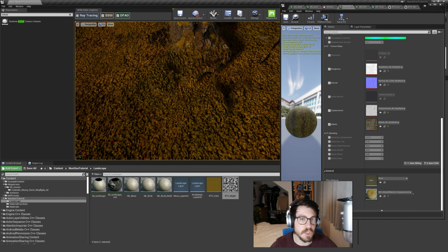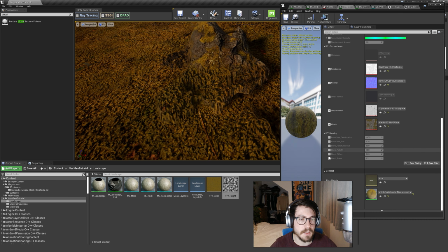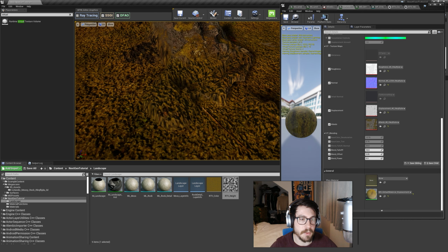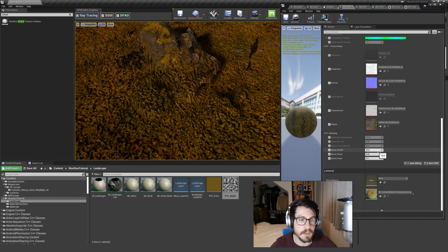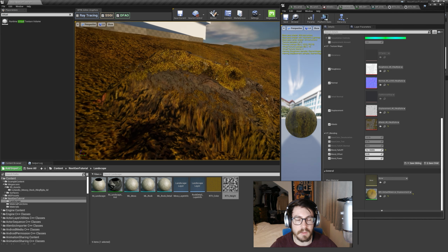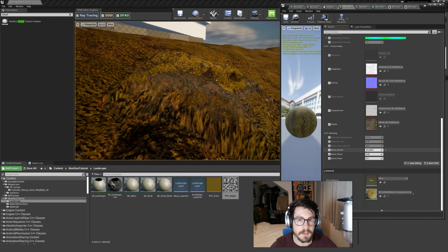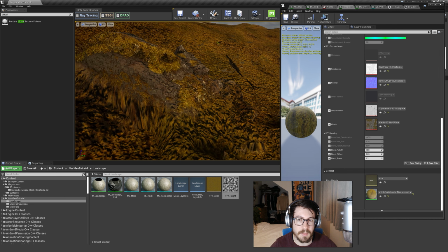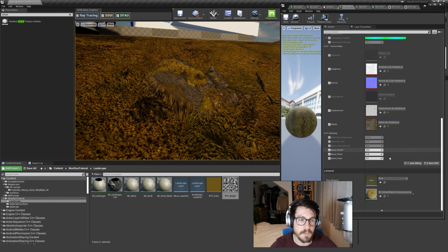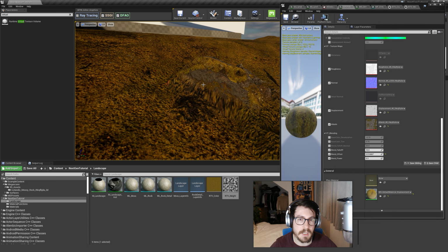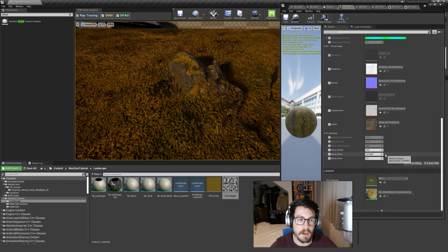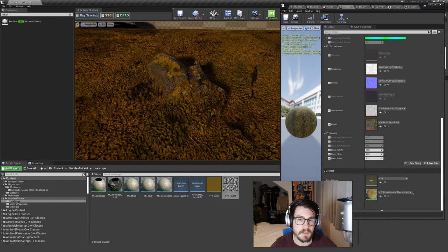And to change this falloff that we added, we can play around with these 3 parameters here, like the blend falloff. You can see that this creeps higher and higher, but the mask is not really nice. I think you want a soft blend but not too wide. And of course you could add a proper mask. We could add a bit of noise in there and change the way this blend works.